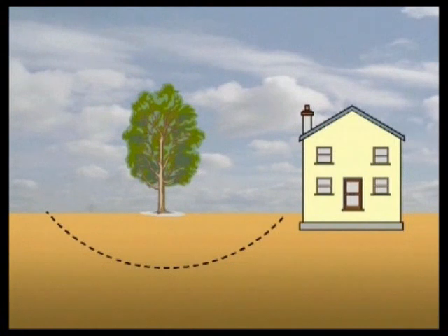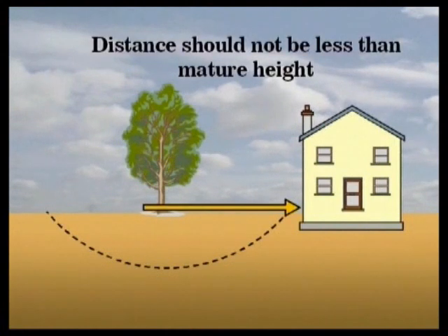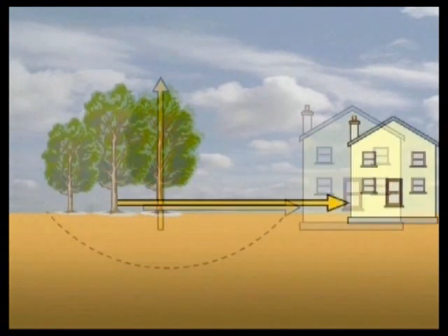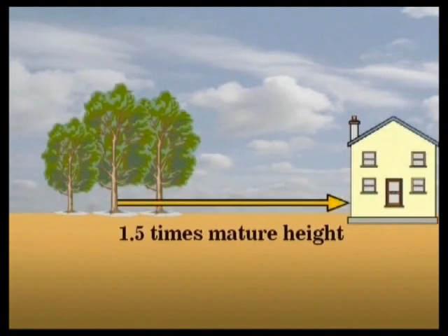To avoid this failure, new trees must be kept well clear of the foundation, usually at least a tree's mature height. Where there are groups of trees, this distance should be increased.